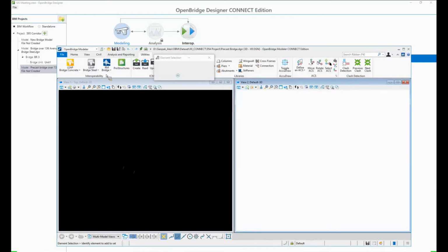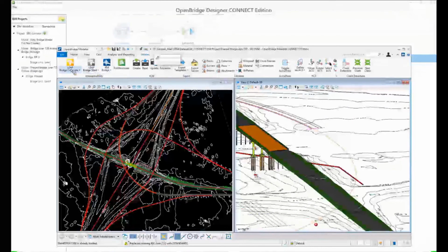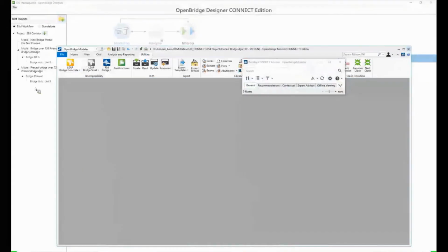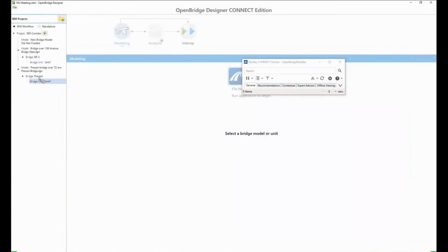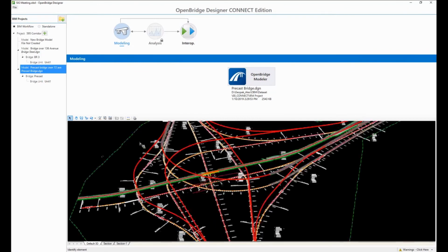So you do, Liam, in your case, send it to RM Bridge. But again, I have another option. I can send it to LEAP and modify that, and when I exit, my point of entry one more time of that analysis software was the BIM model. Here, that information is saved. And now I have a BIM model, and the design is locked. To get into the design, I have to go through the DT to the BIM model to guarantee that I'm not breaking any BIM process. And then you can create as many as you want.